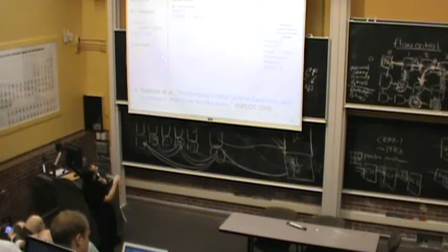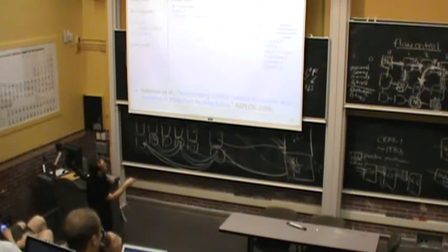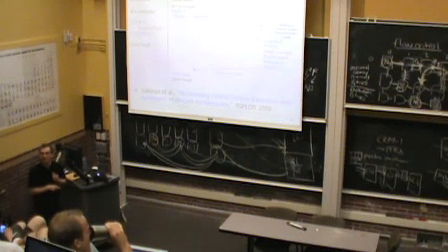And this is what happens in the target PC, essentially the critical section, with some other things, like now we need to actually send the data that's needed by the critical section. So the first thing the large core does is pop A from the stack, because the small core pushed A onto the stack, right? And that's needed in the critical section. It then executes the critical section, pushes the result on the stack, releases the lock, and executes a critical section return instruction, which essentially sends a response back to the small core, and now the small core pops the result and executes the rest.